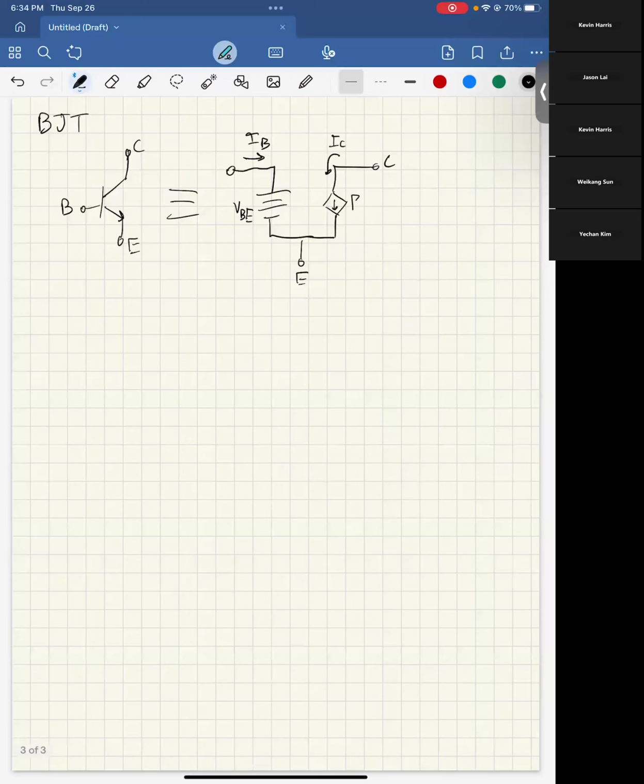And what we find is that we have this beta factor, which is often called the current gain. So what we see here is that IC equals beta times IB, or we'll capitalize that to match the notation there. And from that, through Kirchhoff's current law, because they both go down like here, you can say that IE equals beta plus 1 times IB.